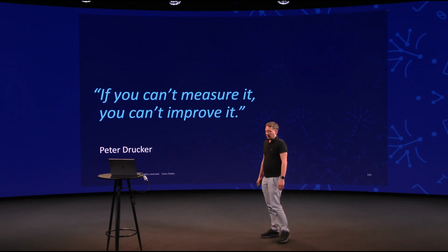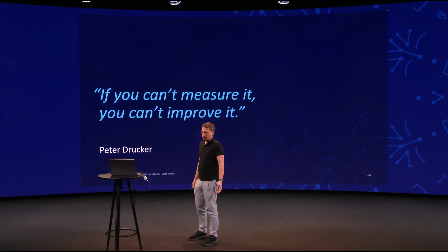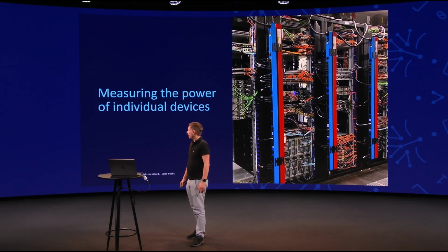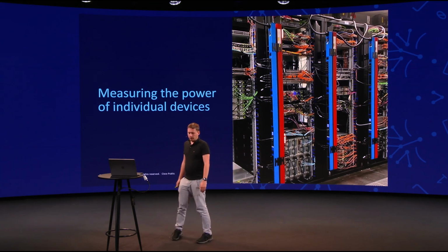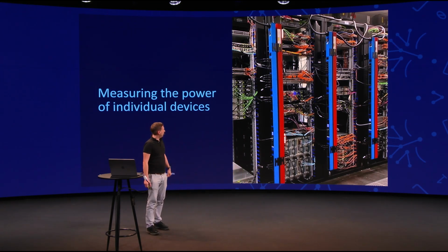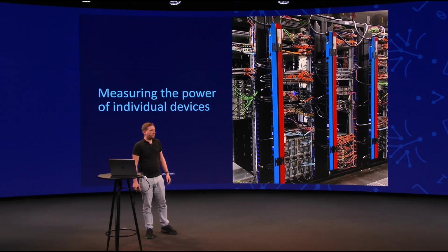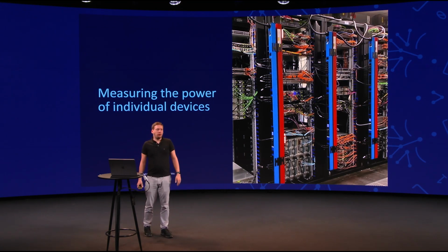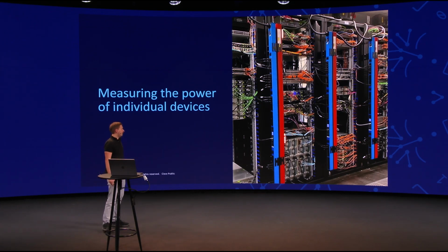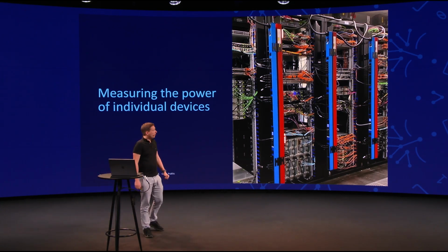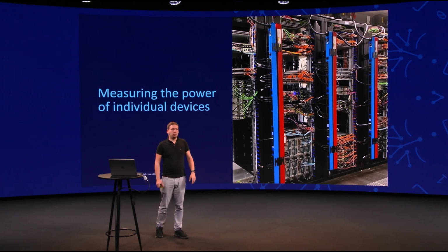Usually, as I mentioned, we have these measurements of energy and power per location. But if we want to go into more detail, how do we actually achieve that? I have here a picture from one of our labs in Vimercate, and what you see first and foremost are those two blue and red bars on each rack. These are of course the PDUs, the power distribution units that feed our devices. The first thought could be, I want to measure my power more granularly, could I tap into those? The answer is maybe, because it depends on your PDU. Some PDUs do have power sensors, but some only measure the whole power of the whole rack.